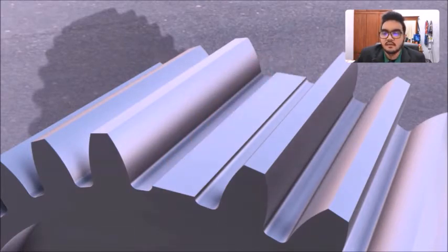This smooth flat surface is then cleaned to ensure no debris or residues before depositing material onto the surface, which will cause defects later on. After that, new material will be deposited onto the surface. For this gear, we use laser metal deposition or LMD to create new teeth for this gear.